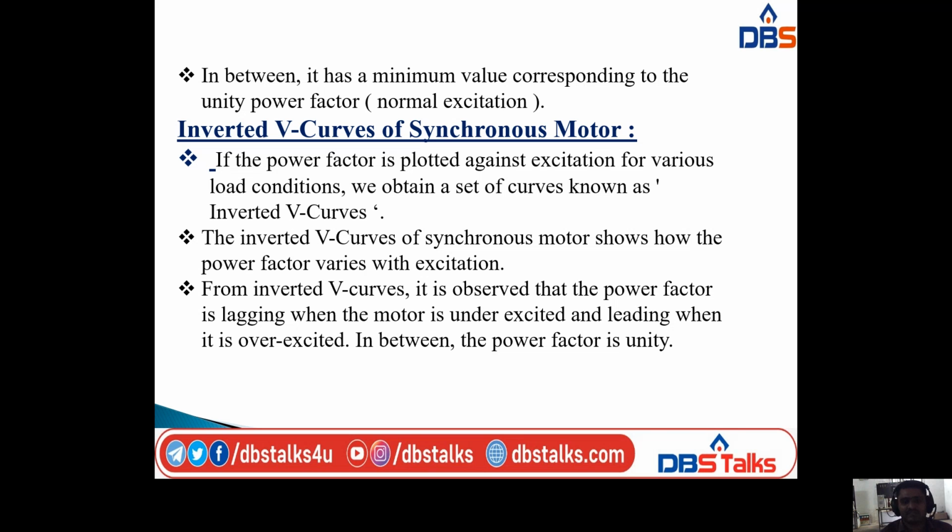From inverted V curves, it is observed that the power factor is lagging when the motor is underexcited and leading when the motor is overexcited. In between, the power factor is unity.